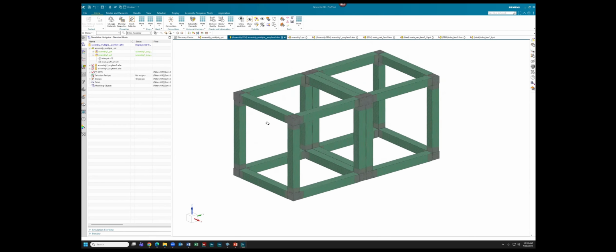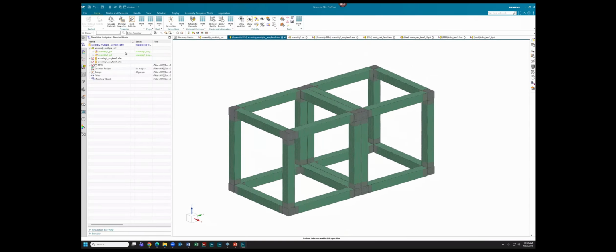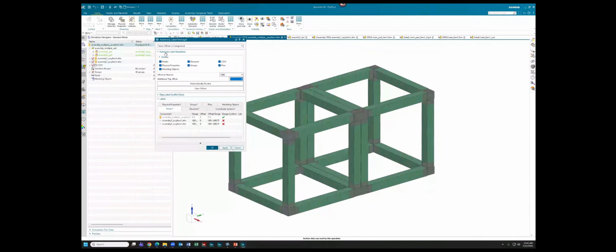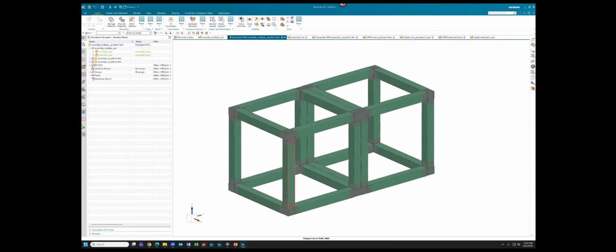I really wanted to showcase that you can, in fact, have nested AFEMs within an AFEM. So once again, you can break out your sub-assemblies to their own AFEMs and then have individual component FEMs within those AFEMs, which is really nice as well. And then once again, we can use the assembly label manager within our assembly FEM to deal with these conflicts automatically. Again, just a huge time saver. Just a click of a button here, and my ID conflicts have been dealt with.